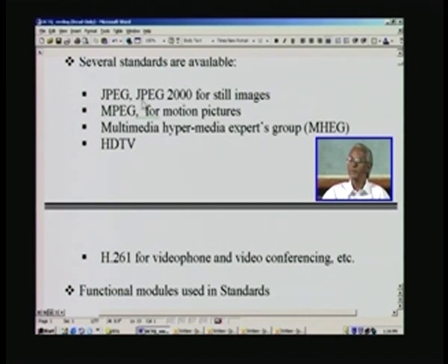This is very computationally intensive when compared to the DCT, and therefore you can't achieve real time speeds for high resolution pictures of the order that we have already seen before, which can be in this design that we are going to present. We will see that very high quality, much greater than the picture size that we have mentioned before, can be achieved by using JPEG or for that matter MPEG, MPEG 1 and 2, and MPEG stands for